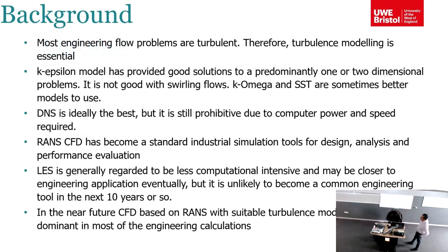Most engineering flow problems are turbulent. Therefore, turbulence modeling is essential, and this is where large errors can come from. When you use a turbulence model, you need to know what turbulence models you use and why different turbulence models are important. For example, if it is a fairly straightforward problem, mostly in one or two dimensions, or if it doesn't have swirl and so on,